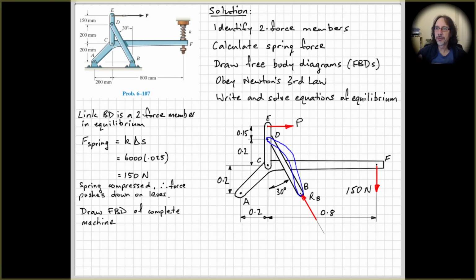Could be shaped like this blue curved link that I put here instead. The fact that this is curved and not straight between B and D doesn't matter. Right? It would still have a reaction force at B here directed along the line joining B to D. And I've got on here now the arrowhead indicating its sense.